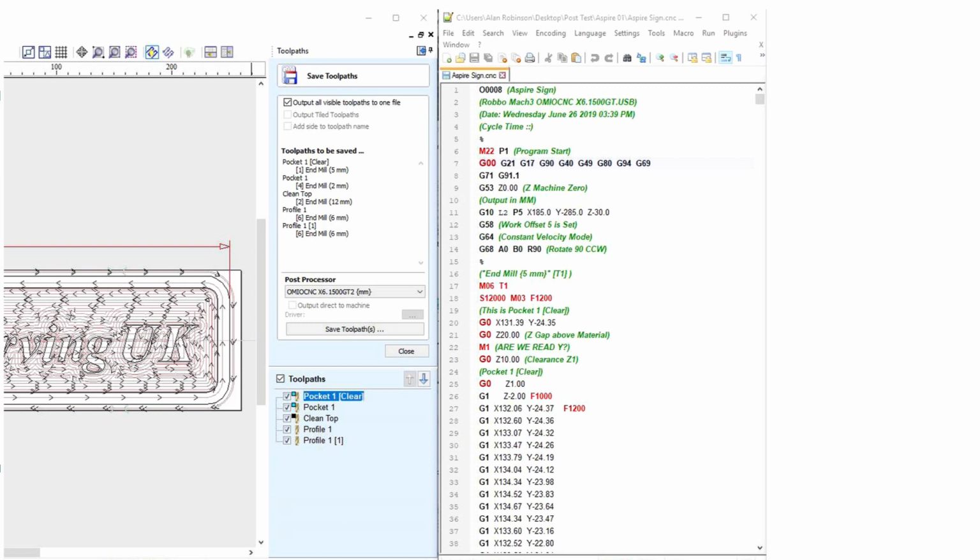G90 and G91 distance mode. Interpretation of Mach 3 code can be in one of two distance modes, absolute or incremental. To go into absolute distance mode, program G90. In absolute distance mode, axis numbers X, Y, Z, A, B, C usually represent positions in terms of the currently active coordinate system. Any exceptions to that rule are described explicitly in this section describing G-codes. To go into incremental distance mode, program G91.